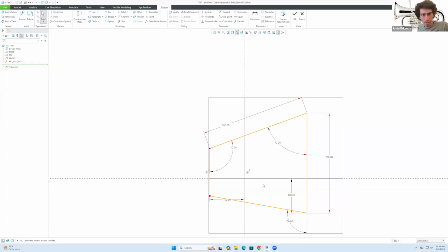Why are construction lines useful? Because if I'm told, all right, I have a figure and I want to do a hole that is 5 centimeters from two edges, I would use the construction lines to denote that distance, 5 centimeters from one side, 5 centimeters from the other, and I will be able to identify where I am. But let me do Control Z. I'll be using them a lot in just a minute. We're going to explore rectangle, circle, arcs later. We'll come back to those in a minute.